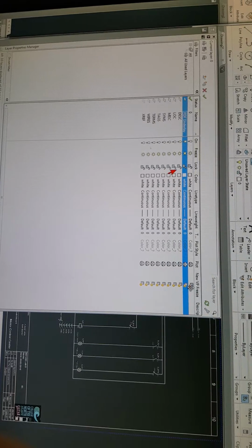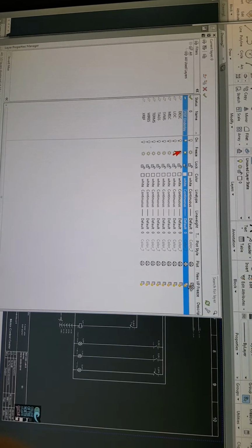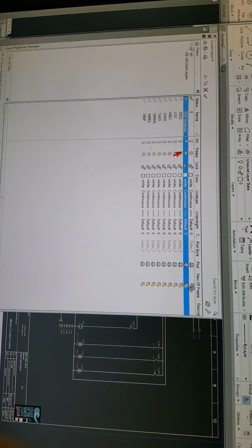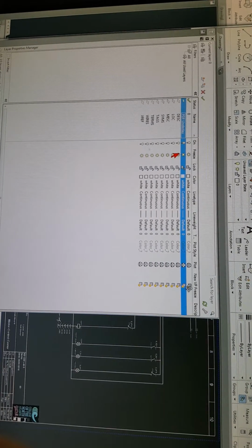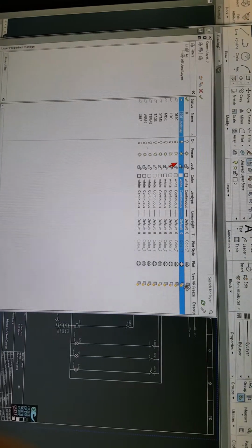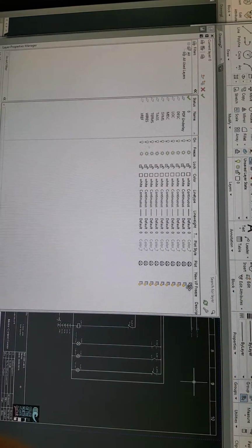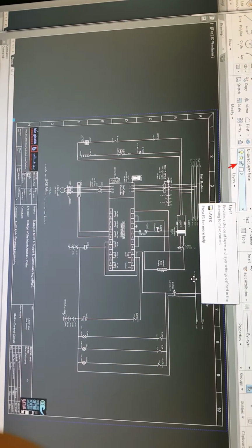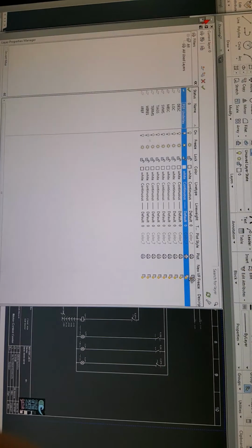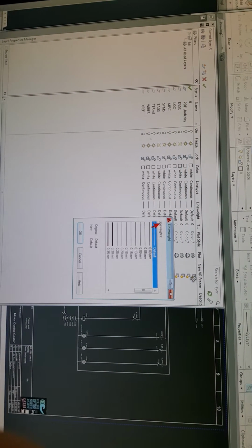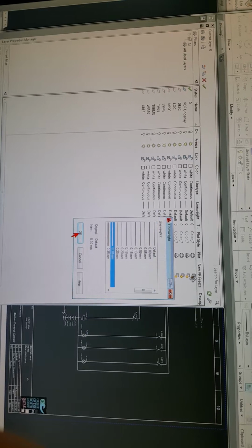Now I need everyone to create a layer. Call it anything, call it image, call it tracing. Do I need to put 0.4? No, that's something different. We're going to put our drawing on layer 0. I would like layer 0 to have a line weight of 0.3. Now I'll show you why.